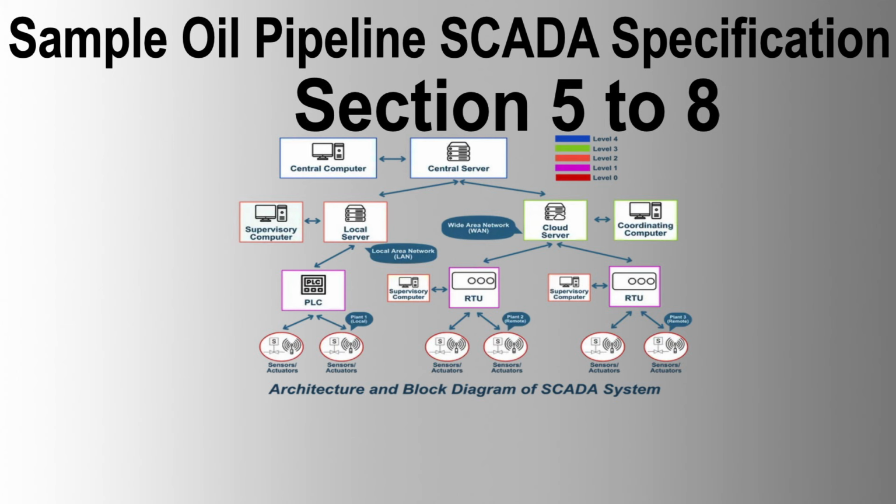6.7.11 Lightning protection. Seller shall address the effects of lightning strike and provide recommendations for lightning strike protection. 6.7.12 Serial link isolation. Serial link isolation relays shall be provided within the field marshalling cabinets, certified suitable for use in a Zone 1 Group 2A T3 hazardous atmosphere. 6.8 Expansion contingency. There shall be an expansion contingency of 25% allowed for FMC terminations and associated subassemblies as indicated in Appendix B.